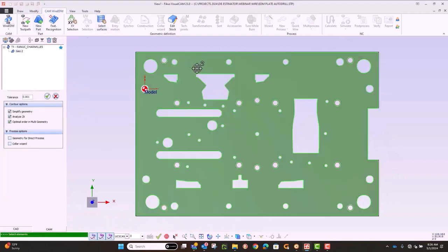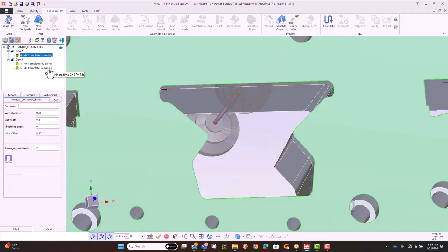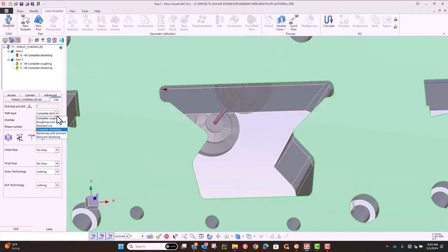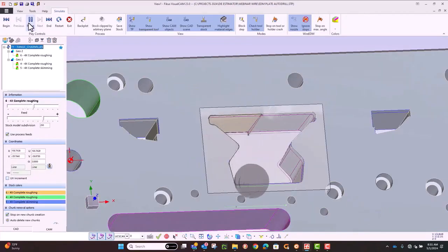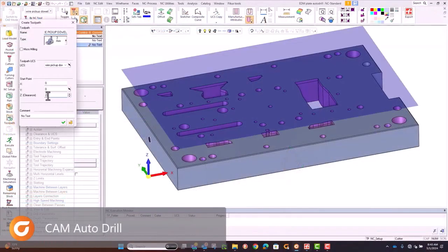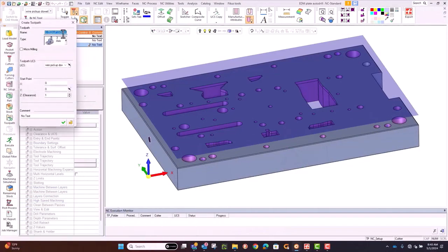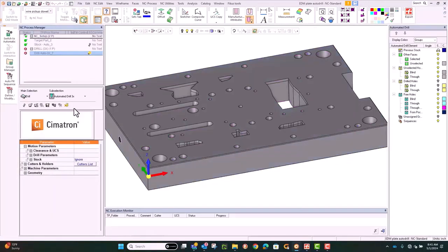Another big part of doing a die is, of course, a wire EDM when it comes to those punch holes. Here at our wire EDM, I'm going to set up one of these punches. I just identify that feature area. It's going to be a variable, or in this case, 4-axis cut. We'll tell it what we want to start with. I'm going to rough cut through the tapered area, then come back, do another rough cut on the land, and finally come back with a finish cut along the land. So very quickly, that also can be saved as a sequence or template and used again.